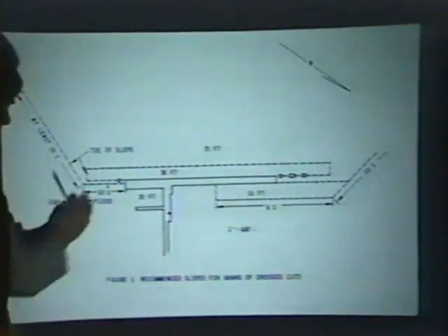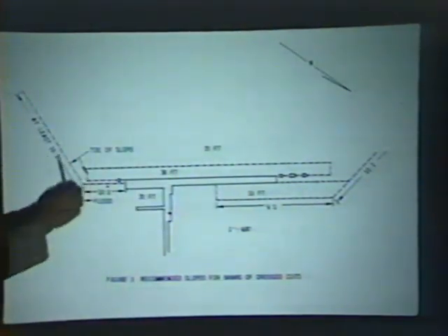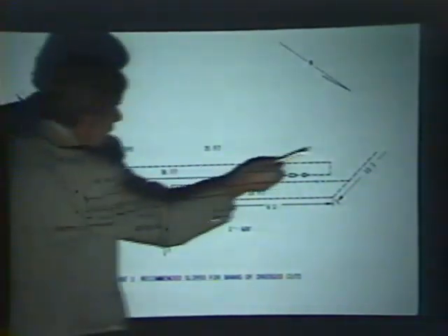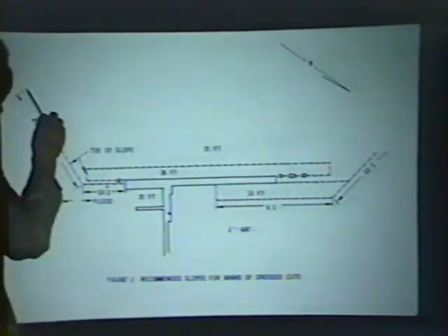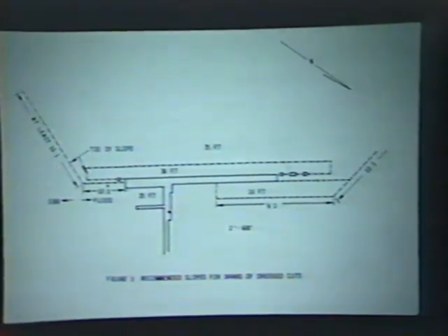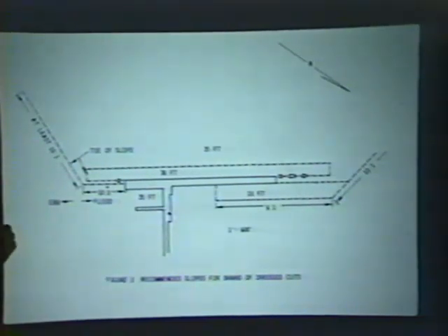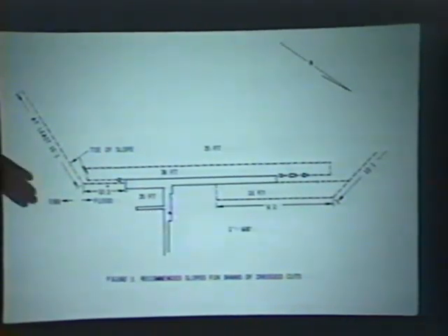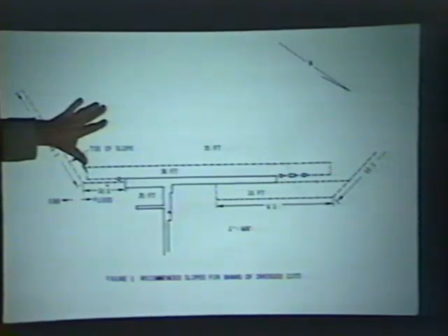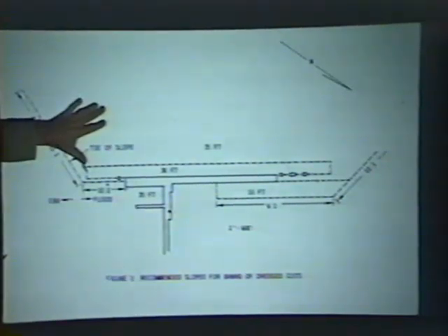Model studies showed that the edge of the cut, this is quite shallow out in here. It doesn't show the depth, but it's quite shallow out in here. The flow, tidal flow across the edge of the cut created eddies, which reduced the bed shear stress and promoted aggregation of the particles. So that the deposition rate was very rapid out in here, out to about, well, it was about, pattern was something like this.